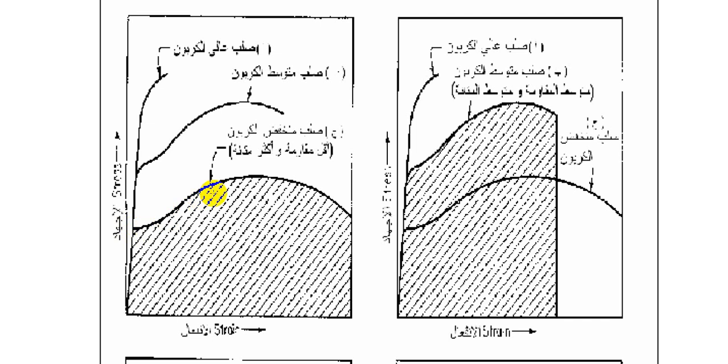The upper yield point and the ultimate tensile strength reach a limit here at the peak, plotted in the stress-strain curve, till reaching the fracture point at which the toughness and ductility are finalized. For the high carbon steel, the strain is plotted horizontally and the stress vertically, in both diagrams, as you can see in front of you.